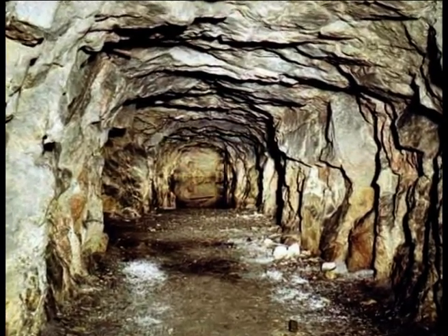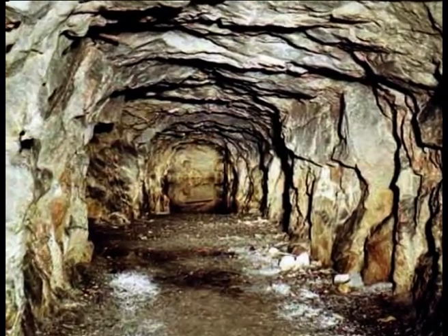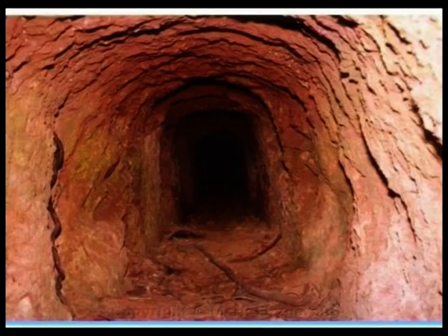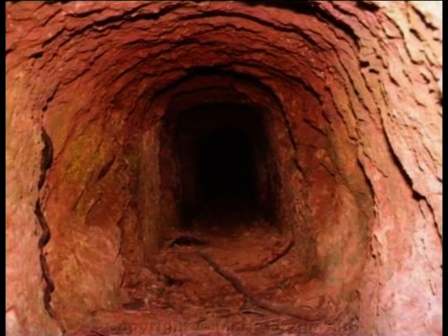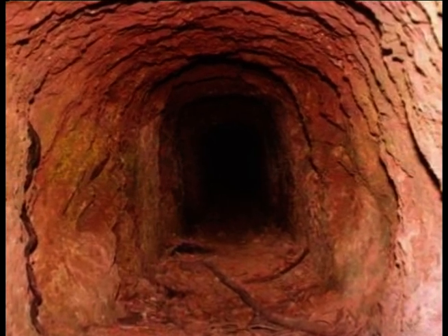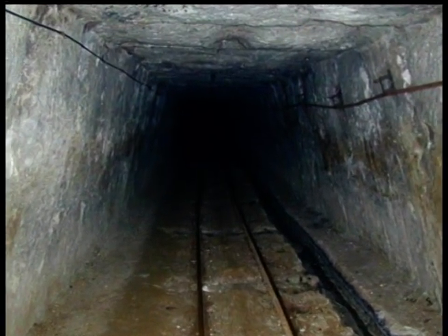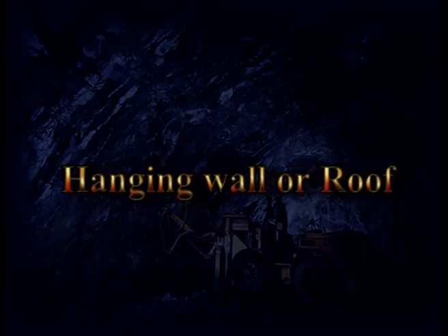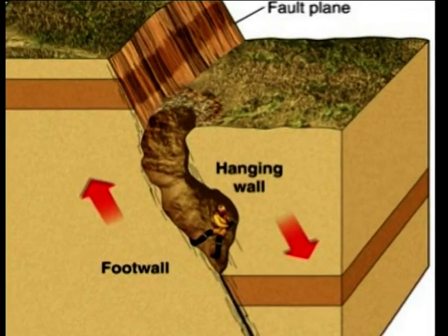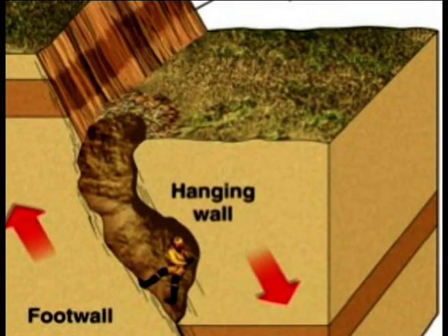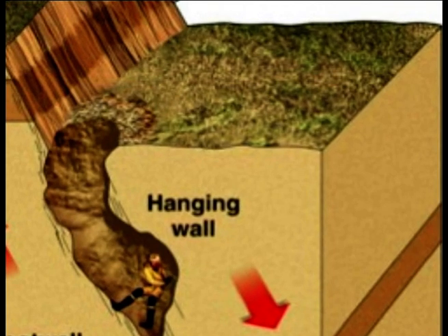A normal tunnel passes from one side of the hill to the other. A shaft is a vertical or inclined excavation which is either square or rectangular in section, lined or unlined. Shafts are openings which serve as a means of entry. There are different types of shafts such as vertical shafts, auxiliary shafts, incline shafts. Hanging wall or roof: the country rock occurring above the vein or ore body or seam is known as hanging wall. In coal mining, it is called roof.